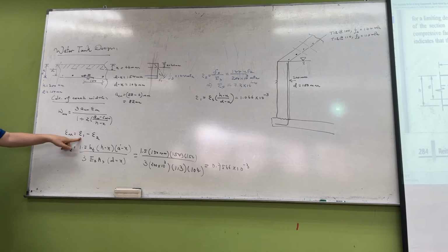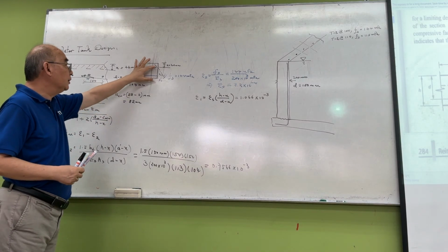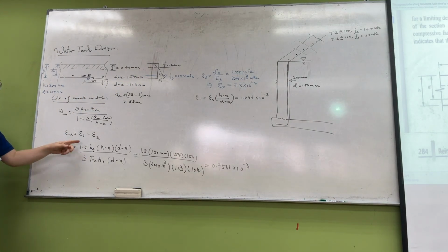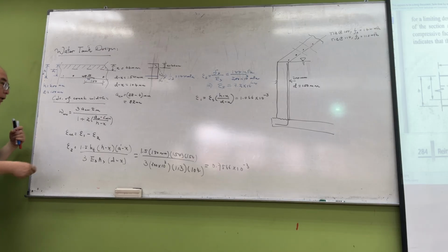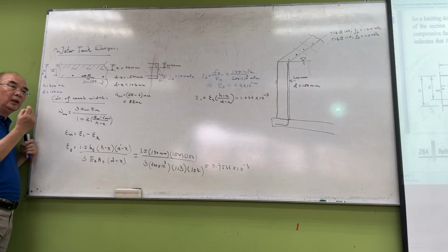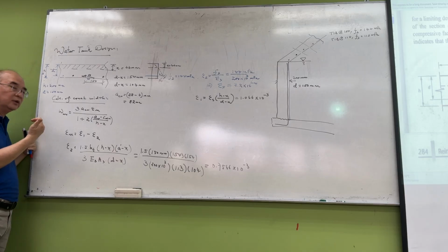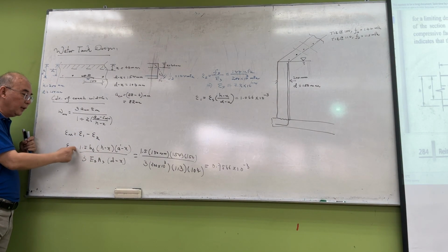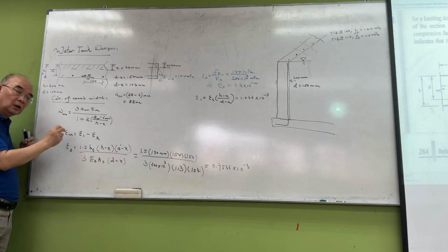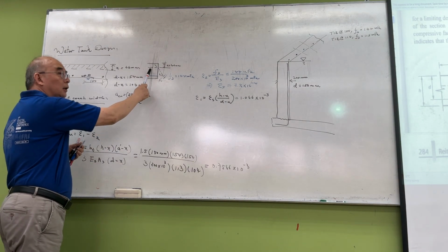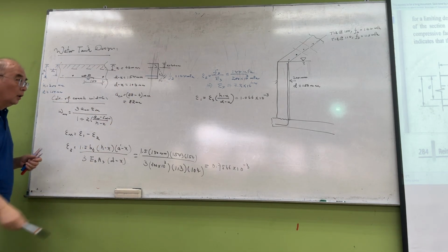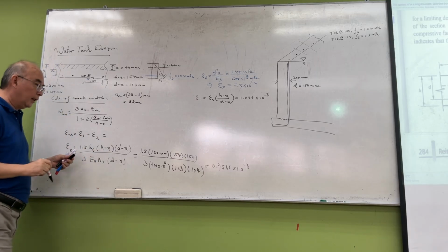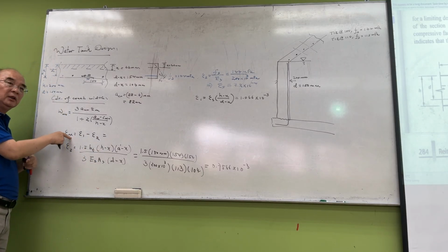So this epsilon 1 is calculated based on the concrete having no tensile strength, right? But when we calculate the crack width, the concrete has a certain tensile strength, and this causes what we call a stiffening effect. So we need to subtract epsilon 2. Epsilon 2 is based on 1.5 MPa of concrete tensile strength in the tensile zone. Okay. So in this case, what is epsilon m? Epsilon m means the mean strain.